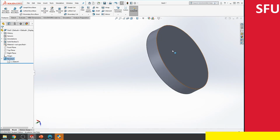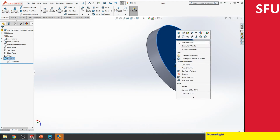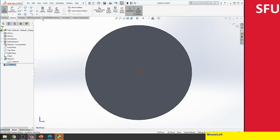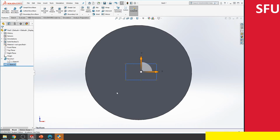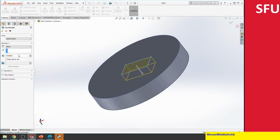And what I can do is select this face and then create a new sketch. And then create parallel to sketch. And then if I wanted to create a rectangular shape or whatever shape I want, I'll say okay. And then this is where the extrude cut comes in. So I go extrude cut and I need to move this around and then blind.